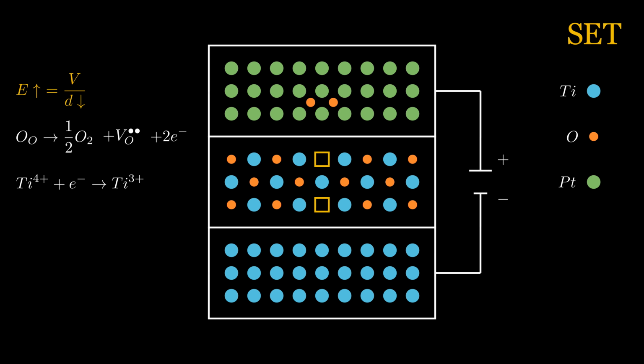Because of the oxide vacancies at the switching layer, a net positive charge is created. And to balance this net positive charge, the incoming electrons from the bottom electrode accumulate at the switching layer and move through the titanium cations, leading the switching layer to N-type semiconductor behavior. Due to the applied electric field, the available electrons give rise to the electrical conductivity of the switching layer. These phenomena ultimately end up forming a conductive filament across the switching layer.